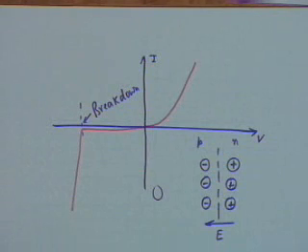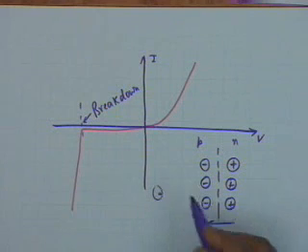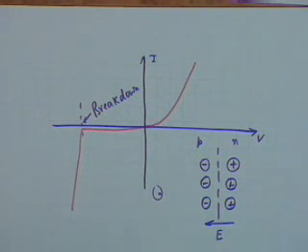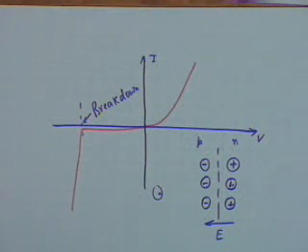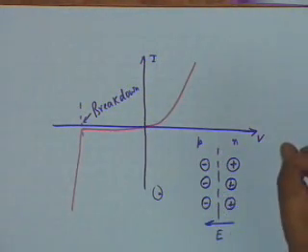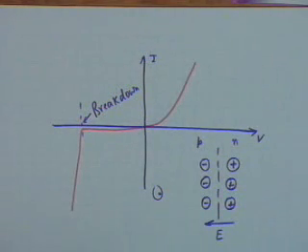Now, if this electric field is so large that it can attract an electron from a covalent bond. You know, there is a silicon atom far removed from the junction, but if the field is so large that it can attract one of the electrons of this covalent bond, that is, if it can cause a rupture of the covalent bond and set electrons free, then as soon as an electron is set free, a hole also is generated.